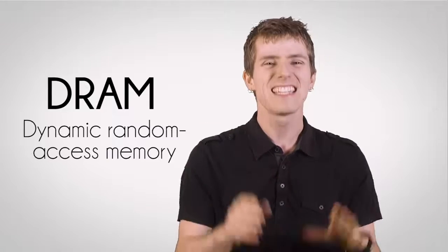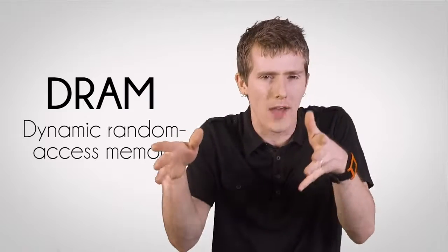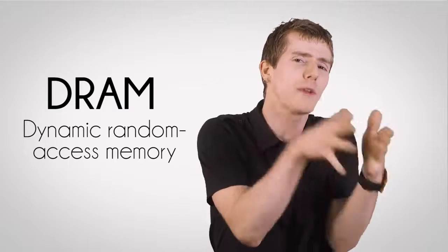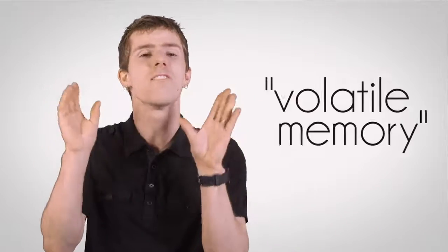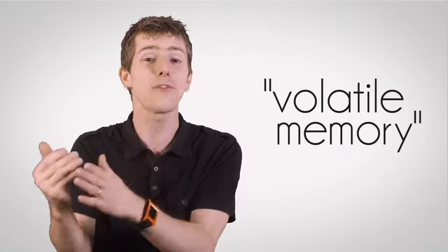DRAM. What most people are referring to when they talk about computer memory. Dynamic Random Access Memory is optimized to sit in a sweet spot where it delivers high performance and high density or capacity at a reasonable cost. DDR3 is an example of DRAM, and it's all volatile memory, which means that once you cut power to it, anything stored in DRAM quickly fades away. And on top of that, this is the dynamic part of DRAM, it's unable to retain data even while it's powered on if it's not being constantly refreshed or rewritten.